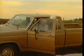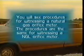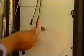Witnessing begins when all parties have arrived at the test site. At that time, always create a good working relationship with the other party. Check the area for hazardous conditions, for example, corrosion, leaks, snakes, wasps, etc. Check to see that the meter station has been operating correctly.